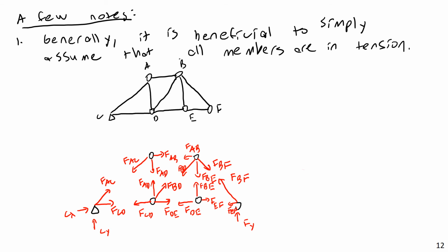If you have a truss in positive bending, when something is bending in kind of a smiley face shape like this, say from a downward load like that, generally the top chord is in compression and the bottom chord is in tension. The chord refers to the line of truss members, so member AC here, member AB, and member BF. So this here is in almost all cases impossible, but that's still fine.